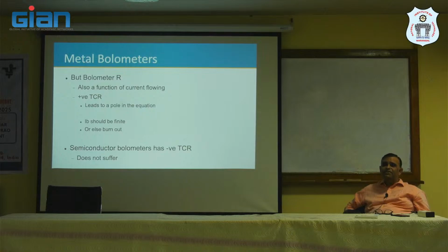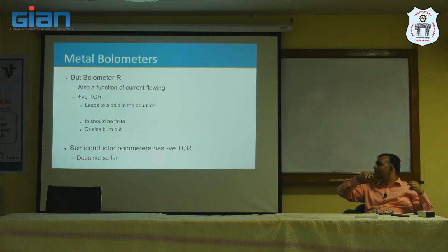Now there is something else which one should remember when we have a sensor whose resistance is changing with temperature. Generally we measure electrical sensors by passing a current through them. So if my resistance is increasing, what is increasing? My voltage demand. Okay? Agreed? So we said metal based sensors, their resistance increases with temperature, which in turn means my voltage demand is increasing.